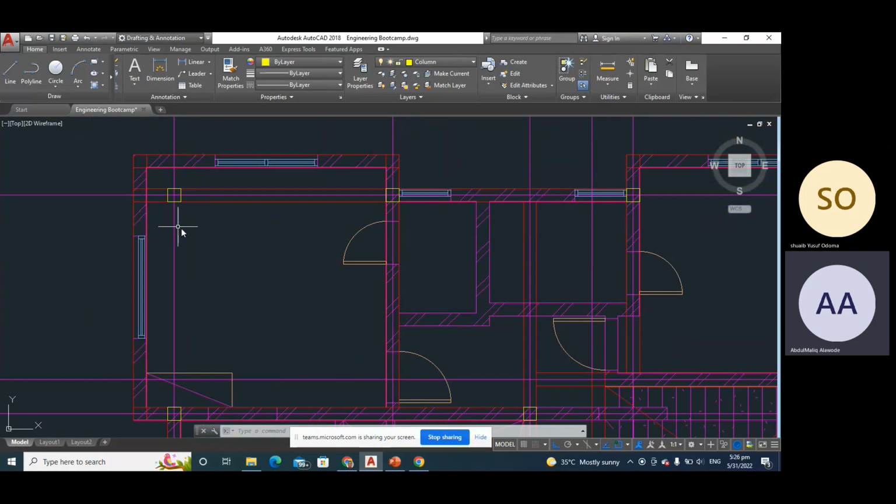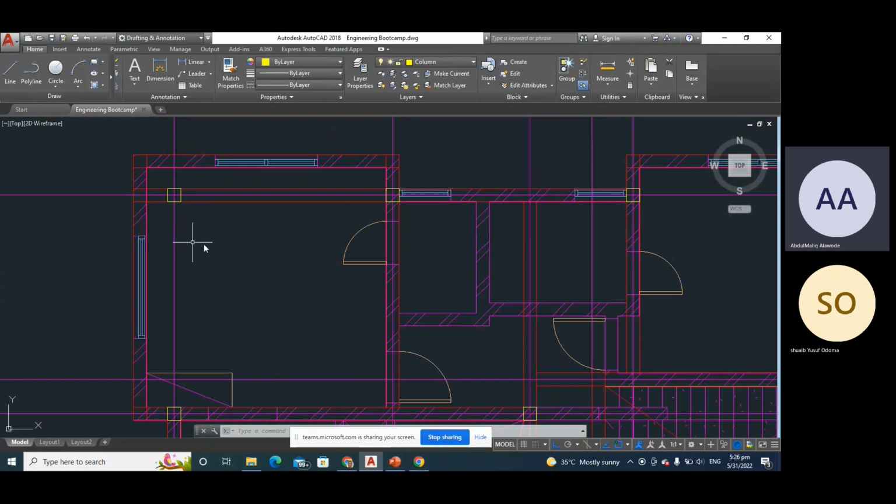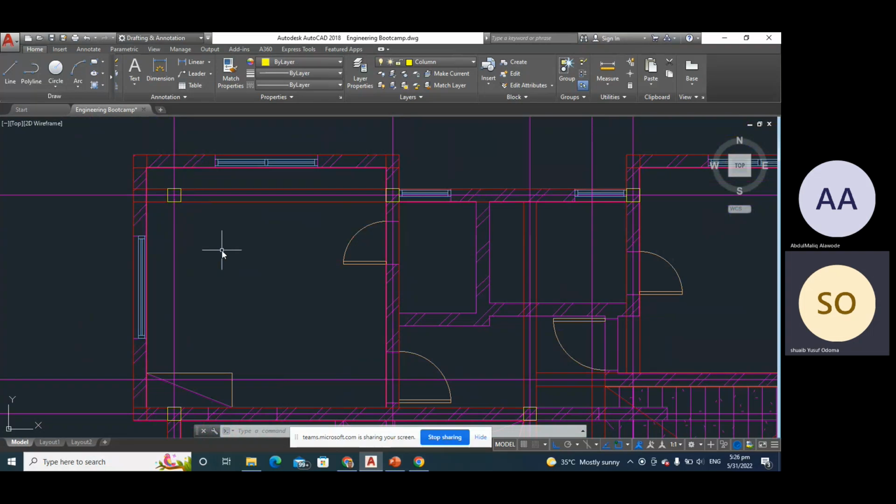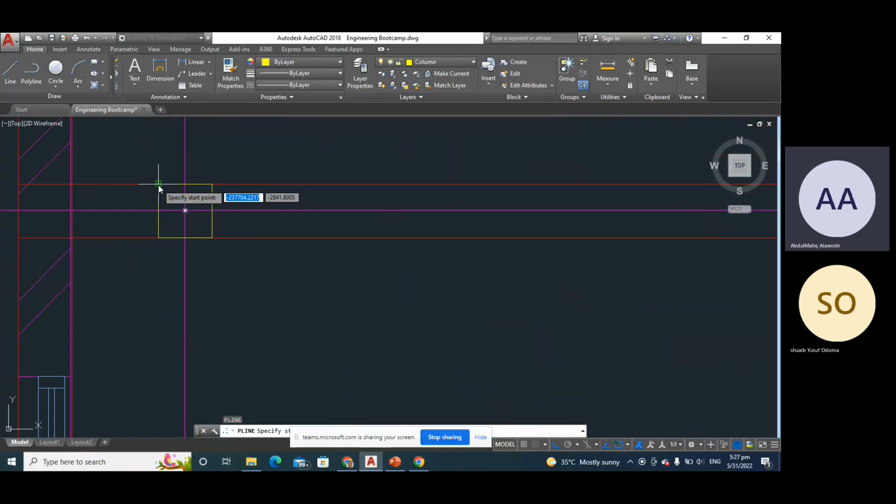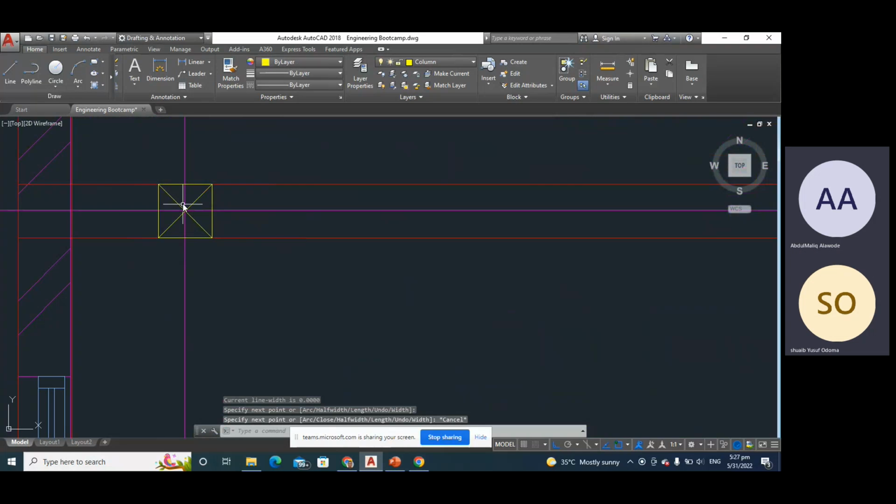All right. So now let's start with this column. Can it go? It can go. So what we do is we strike it off. There are different ways that people use in denoting columns that terminate, but I prefer to use this strike. You know, it's cancel. That means it is stopping on that floor. That's what that means, canceling it out.